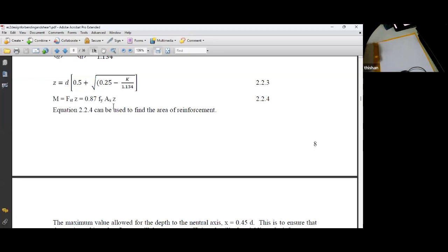The first is the preliminary design, where you get the general arrangement drawing properly done, or when you are selecting the structural form to be used, looking at alternative slab systems and coming up with the most economical slab system. That is the preliminary part of the design. If you get the preliminary part correct, we can do an economical design. Otherwise, you can still do a design.